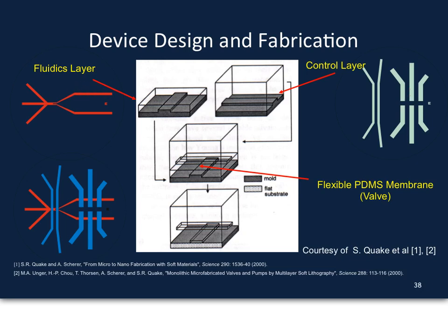So in actually fabricating it, what you do is you create a relatively thin fluidics layer and then a larger control layer just so that you have some mechanical stability, so you have overall a tall device. And the membrane in between is flexible and thin, and so if you increase the pressure in these channels, that membrane will push down and choke off flow through the fluidics layer.